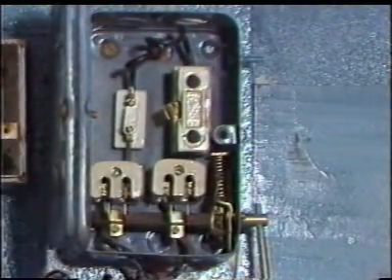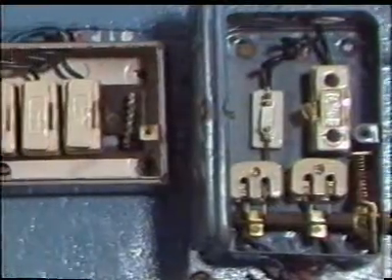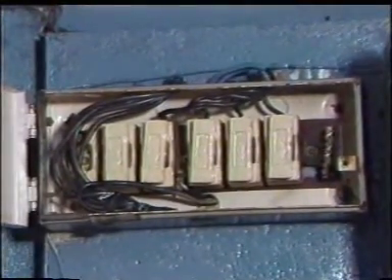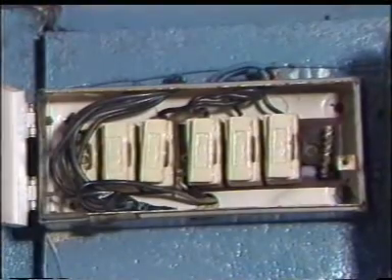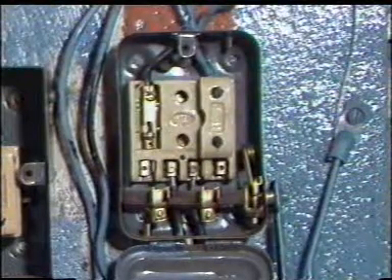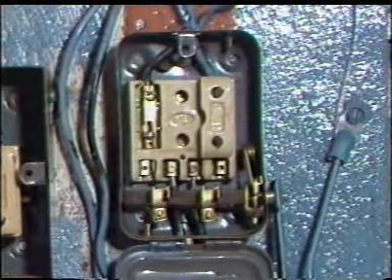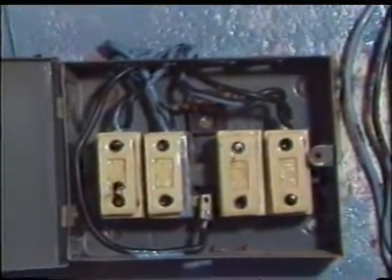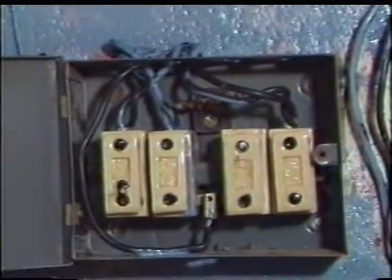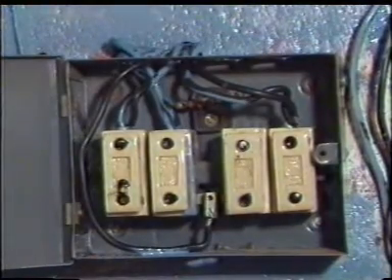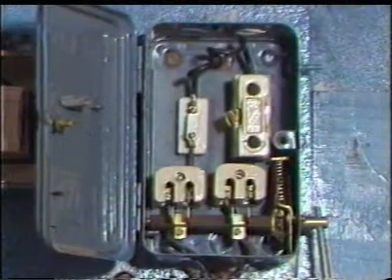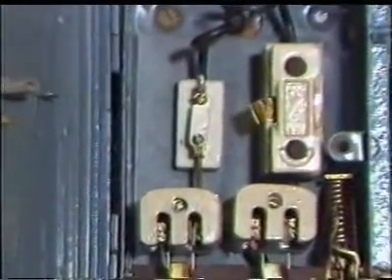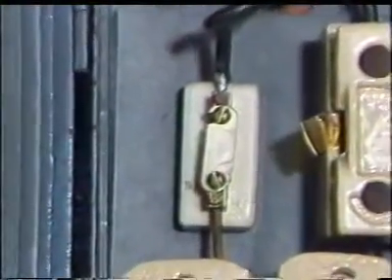This is the main switch and distribution box for light circuits. Similarly, there is a separate main switch and a distribution box for power circuits. The line and the neutral is taken forward by incorporating the fuse in the line and a link in the neutral.